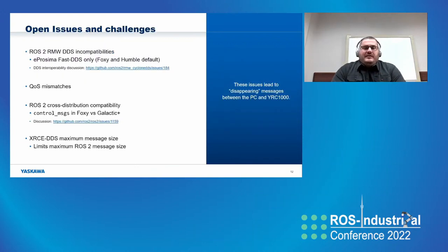We have had a few open issues that have caused us some trouble. For instance, with the various DDS implementations out there, we are currently only compatible with Fast DDS from eProsima. If you're using, say, Galactic, the default DDS is actually Cyclone, and if you try to use that in conjunction with MotoROS2, it does not like that. So you can still use Galactic with MotoROS2, but you do need to change everything to use Fast DDS.